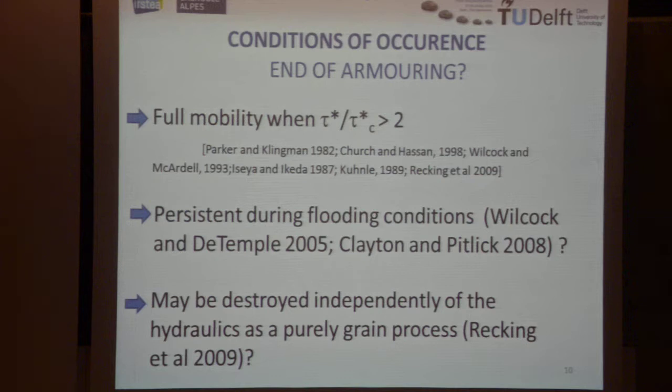What does stop armoring? Actually, usually you consider that for transport stage higher than 2, the full mobility is observed. But some people think that it may be persistent during flooding. And also what we will see today is that maybe the armor can also be destroyed independently of the hydraulics, as a purely granular process.